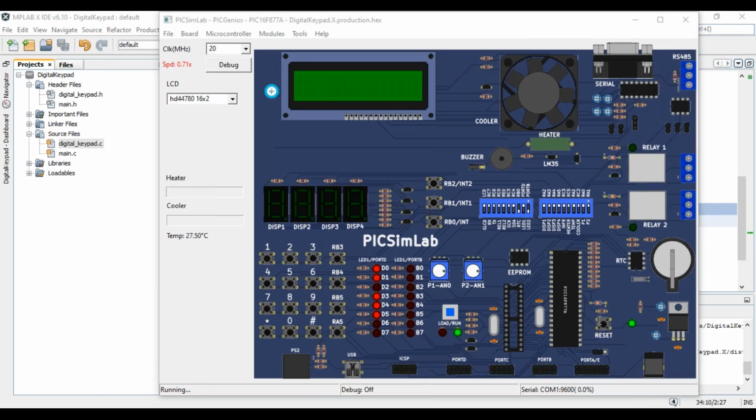Right now it's a virtual box and we can press one key at a time. But on a physical board, if we press two keys at a time, what would be the output at the same time? Would it display the LED glow of the one pressed first? When you go with the physical board, if you press switch 1 and switch 2 at the same time, both RB0 and RB1 will fall to 0. So you will be able to see the response with respect to the LED.